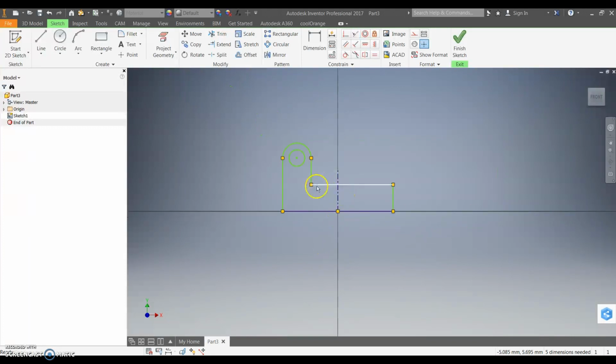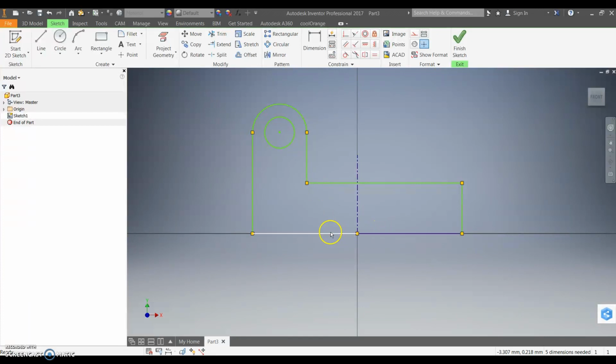Now you might be wondering, we've only got two dark blue constraint lines which don't change dimension, and the rest is green. So one way to test that, if you're not sure why it's still green, you can click and drag it. So I've done all the geometric constraints we can. Now we just need to add some dimensional constraints to show the size of this drawing.